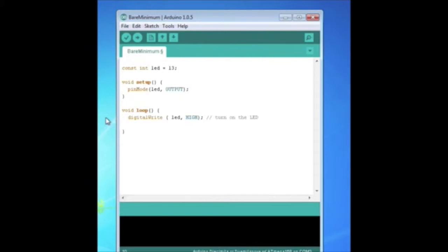Right? Now I want it to stay like that for maybe 1 second. The default Arduino functions give you a delay function, but the default delay function accepts a parameter in milliseconds. I want 1 second, so it's basically 1000 milliseconds. I just pass the parameter 1000 to the delay function.